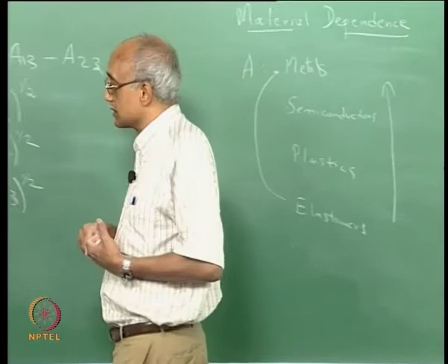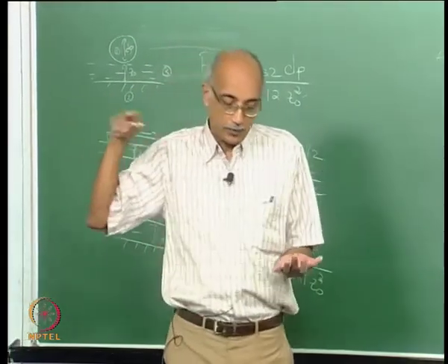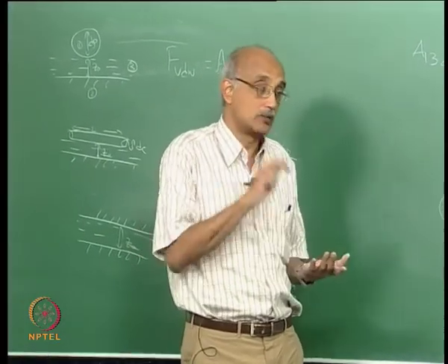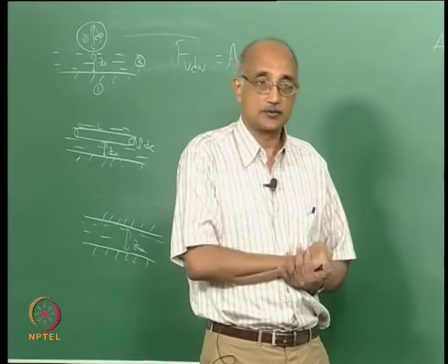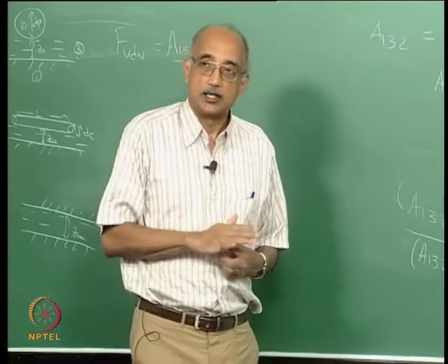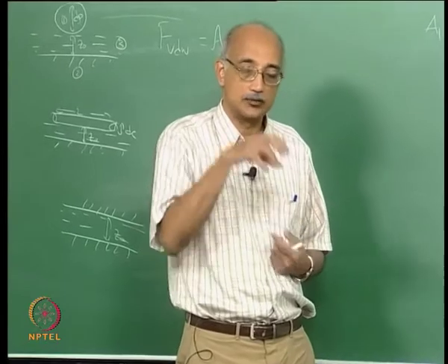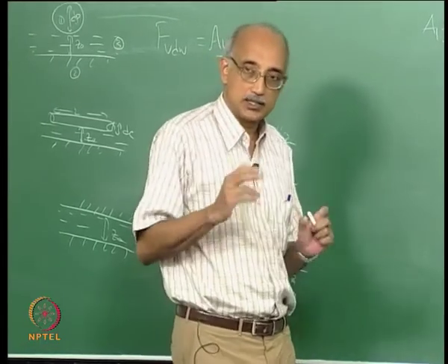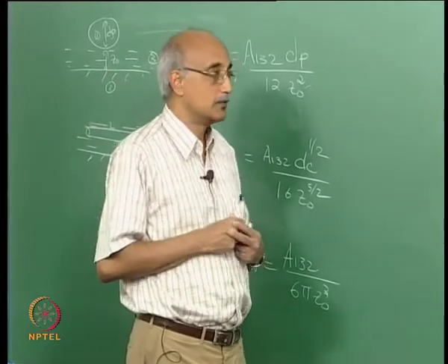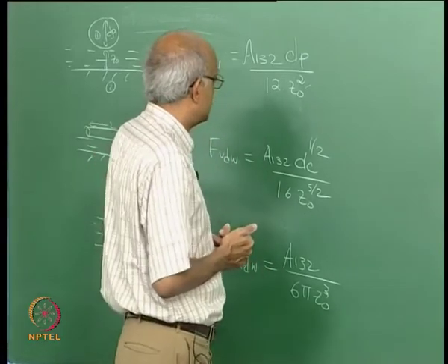Well, one is this Z0 in the denominator, right. As the material deforms, the particle can essentially make much more intimate contact with the surface. So remember we talked about the equilibrium distance of separation, that can drop to virtually 0 when you have a deformable material surface or even a deformable particle. In both cases the intimacy of contact between the two approaching surfaces will be much more, which means that the values of Z0 will be much smaller. And the other reason is